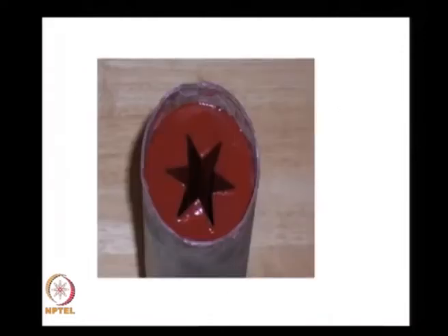Now I show a picture of this grain. Instead of having the grain circular on the inside, I wrinkle the surface such that I have something like a star shape, and this star shape is happening all along the grain surface. Now, what is going to happen? The inner burning surface area S_b is going to be much larger. S_b is going to be the perimeter of this star multiplied by the length along the grain, that is the initial burning surface area, and therefore the pressure and the thrust will be much higher compared to what it would have been had it been pi d naught.